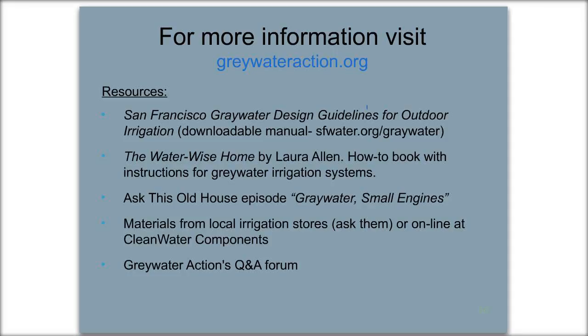Does the mulch need to be replaced regularly? Yeah, great question. I forgot to mention the maintenance. On the simple systems, the maintenance is replacing the mulch, and it's about once a year, maybe once every 2 years. It depends on how much flow is going through your system and the size of wood chips you started with. So the less flow and the bigger wood chips, the longer the maintenance intervals. Sometimes it can be every 3 years if you have big wood chips and not a lot of flow.